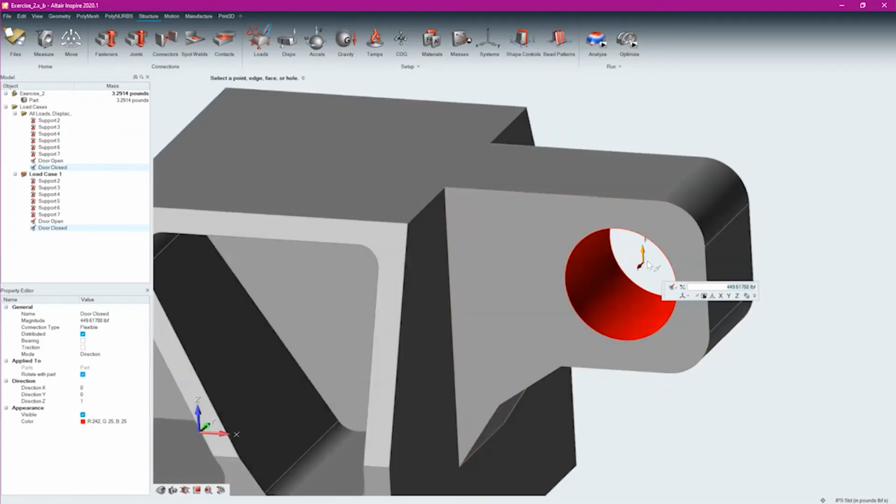Equivalent force, which is going to come off probably at a 45 here because they're close to the same thing. But that can't happen. We have this function, this tool within linear static analysis that's called the load case. And a load case, quite simply, is a combination of a force or multiple forces with a support or multiple supports that are going to define some sort of loading scenario. And that's exactly what we have here.